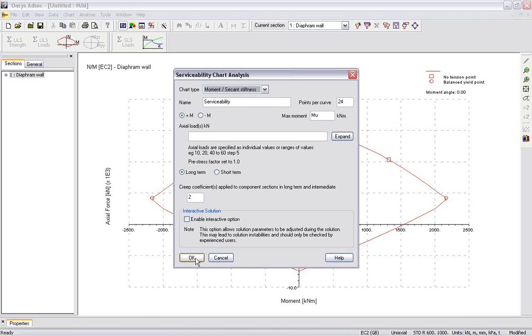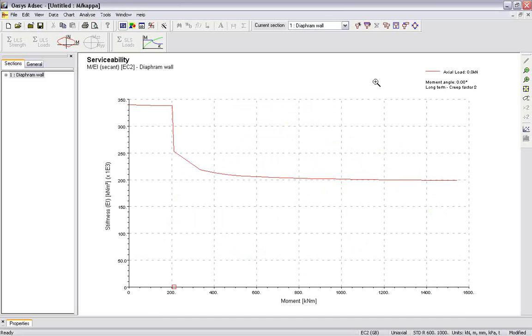And likewise we can get the stiffness out, and you see for a given axial load, which is 0 in this case, it's a retaining wall, you can read off the moments and then find the cracked section stiffness. So you can see here the concrete is cracking at this point, and then the reinforcement is beginning to yield and takes up the load until it finally fails over here. This gives you the EI that you can pass back into Frew and repeat your analysis if required.